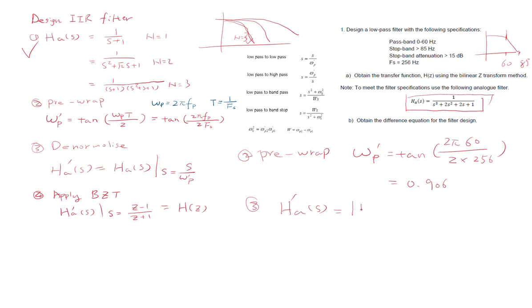We're gonna replace the s with s over omega p hat, because it's low pass filter.